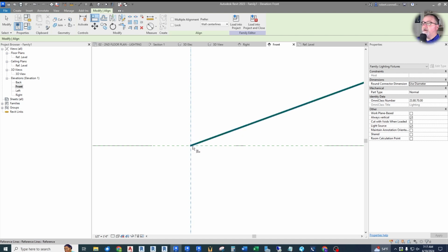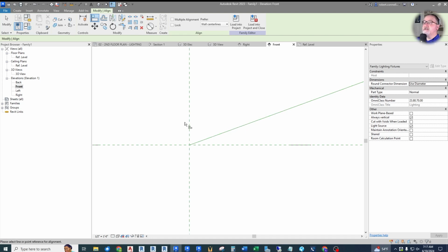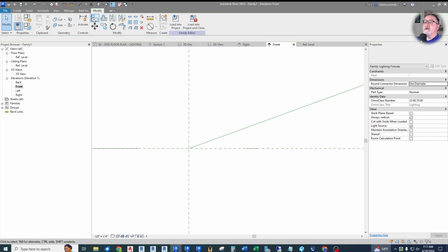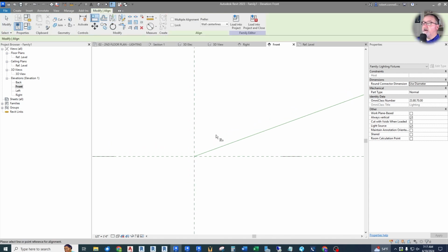See how that popped? You can see a little bit. You get there, the green line kind of pops. If I go to thin lines, let's see if that helps. A little bit, yeah. So you can see a little bit of a pop right there. I have to just start over again because I interrupted it with the thin lines. To there and to the point, and then lock it. So I locked the end point to that vertical.